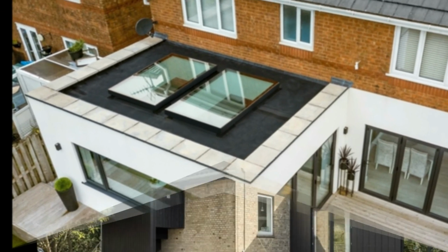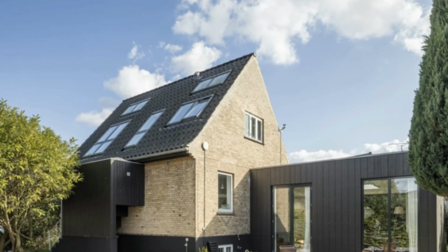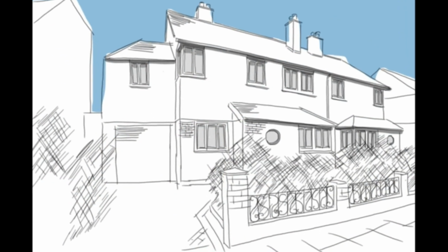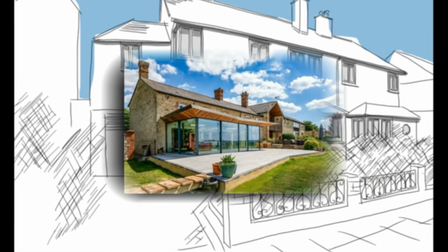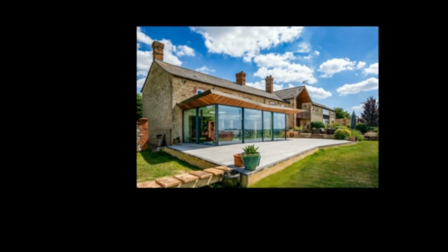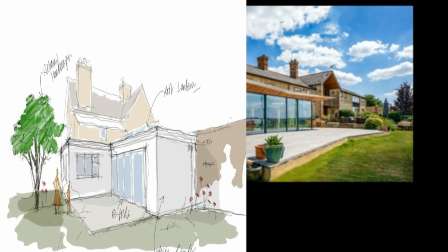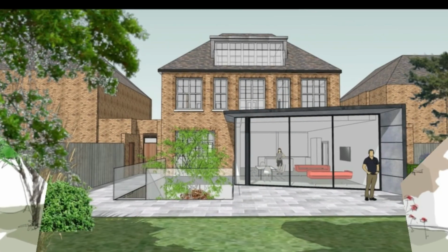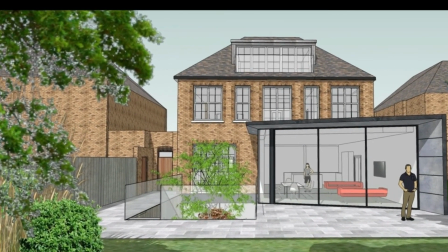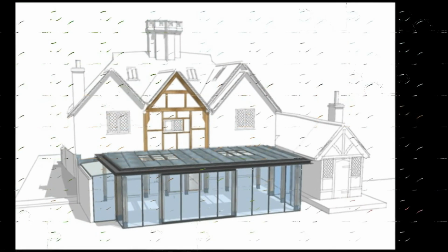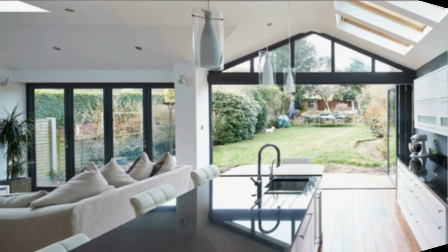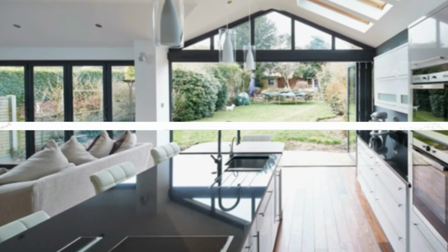Once we are happy with the new layouts, we will then walk you through the planning application process and show you how to provide all you need for a valid planning application. Once we have a planning approval, we will need to prepare building regulation drawings, and for this phase we will teach you how to create detailed drawings and detailed sections for foundations, floors, roofs, electrical, heating, drainage, and everything else you need to get approval from building control.